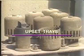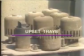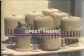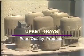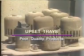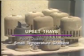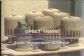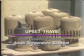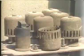Upset trays are usually caused by excessive vapor velocities, by the sudden vaporization of water, or by liquid surges in the bottom of the tower. Upset trays do not fractionate properly because vapors are not forced to bubble through the liquid on the trays. As a result, the liquid on a series of upset trays will have the same composition and will exhibit little temperature difference. Since it is easier for vapors to flow around upset trays than through bubble caps, a tower with upset trays will usually exhibit a decrease in differential pressure.